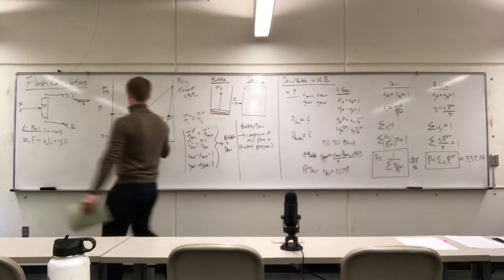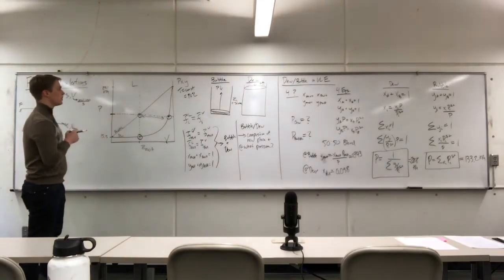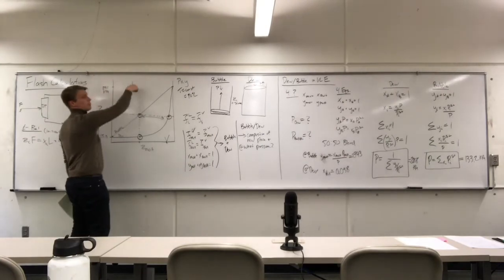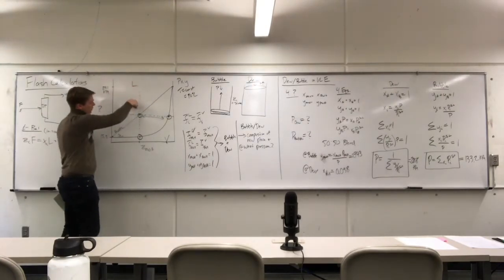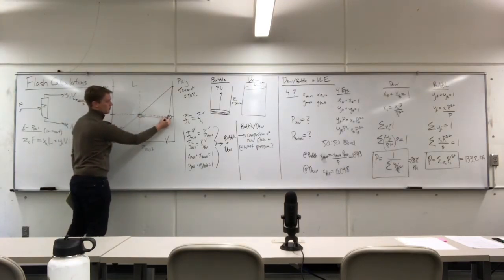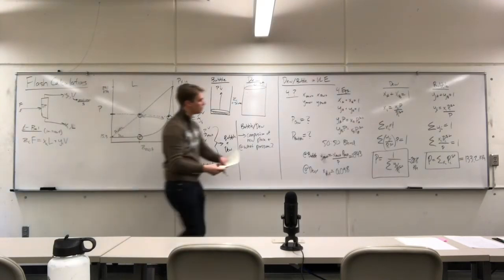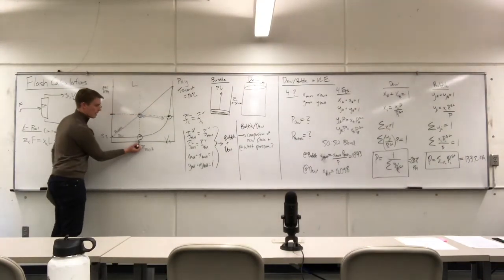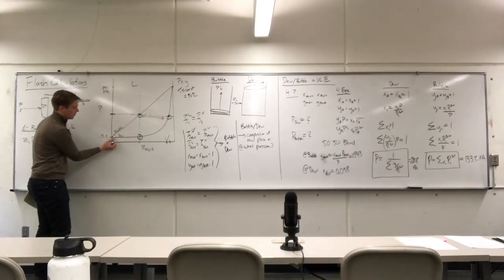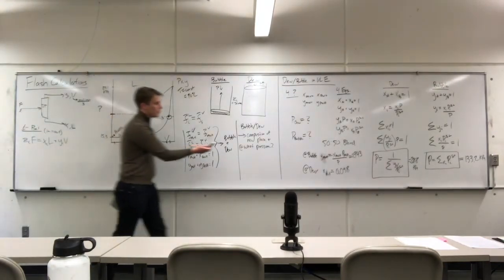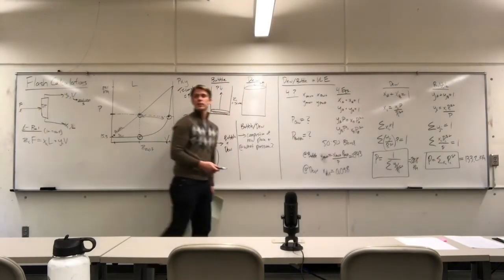Let's see if this makes sense, if I drew my diagram at all reasonably well. So first one here, the bubble curve, we have a 50-50 mixture, right? Bubble is all liquid transitioning to vapor. We travel down. Once we hit here, that means that I should have a very high composition of methanol in the vapor phase, and indeed I do. In this case, it's about 95%. Now if I do the opposite, I have a 50-50 mixture of pure liquid. I draw the line over here. I should have a very low composition of methanol in the liquid phase. And indeed, I also get a similar response, about 6%.